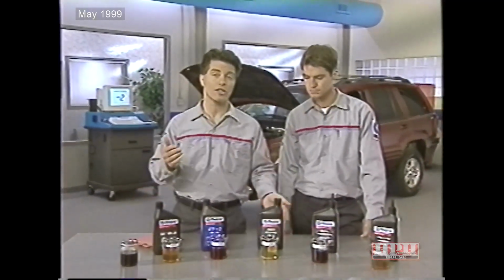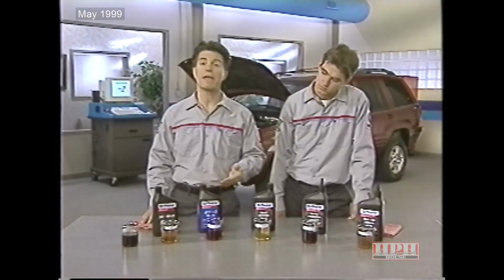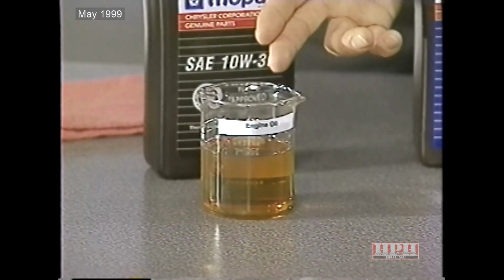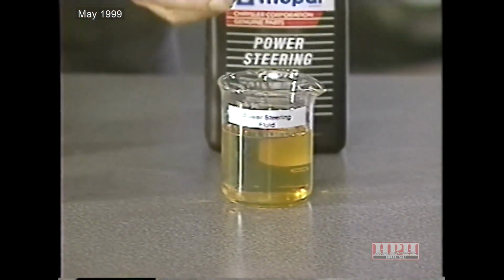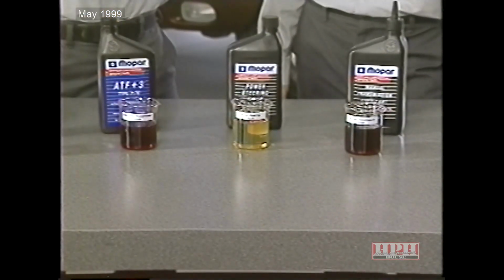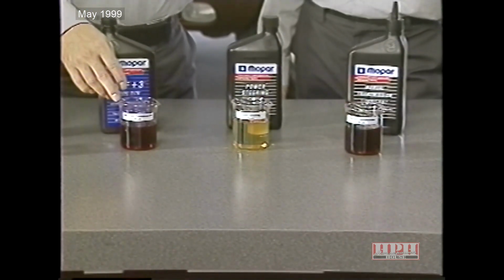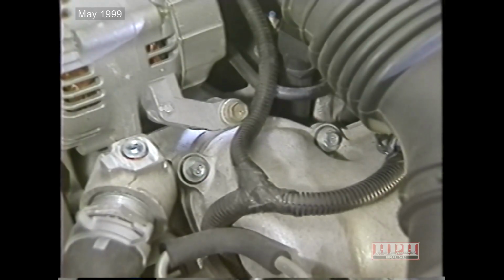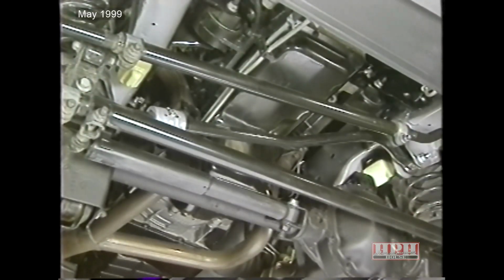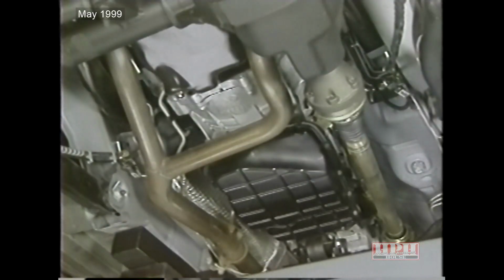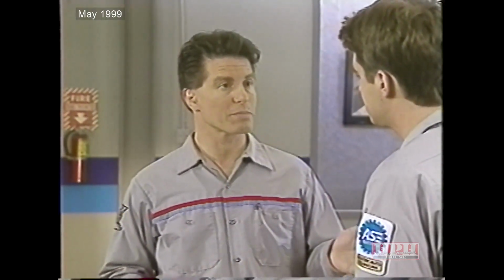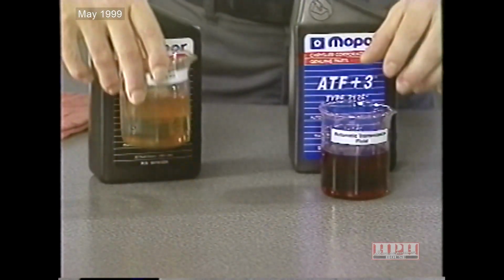Also, many of the fluids that are used from vehicle to vehicle are the same color, or pretty close, making it difficult to distinguish one from another. For example, engine oil is amber, but so is power steering fluid, while automatic transmission fluid is red, and manual transmission fluid is brownish red. Obviously, the location of the leak on the vehicle can help to narrow down the type of fluid, but not all of the time. If you aren't sure what the fluid is by looking at it, try smelling it.